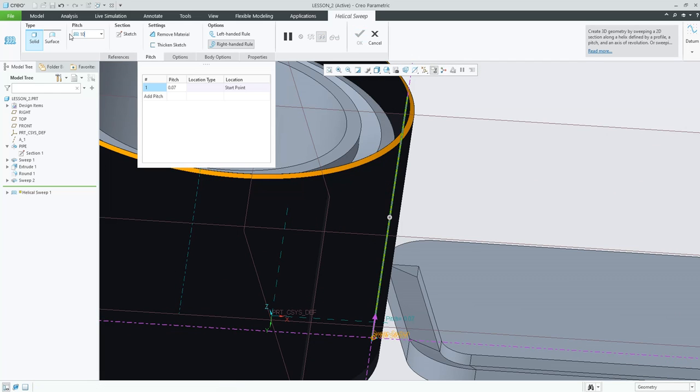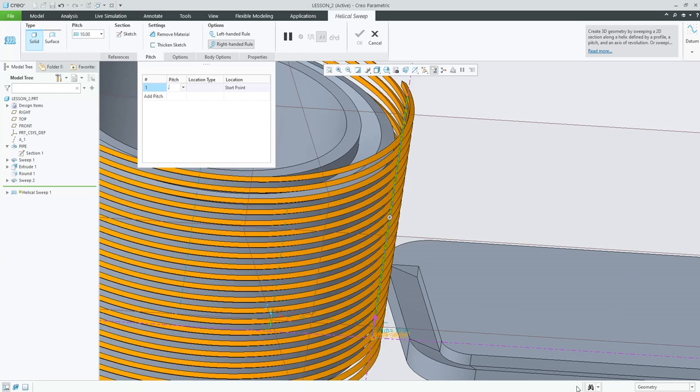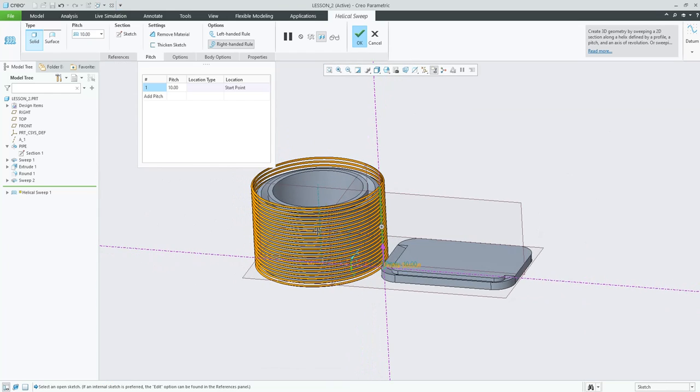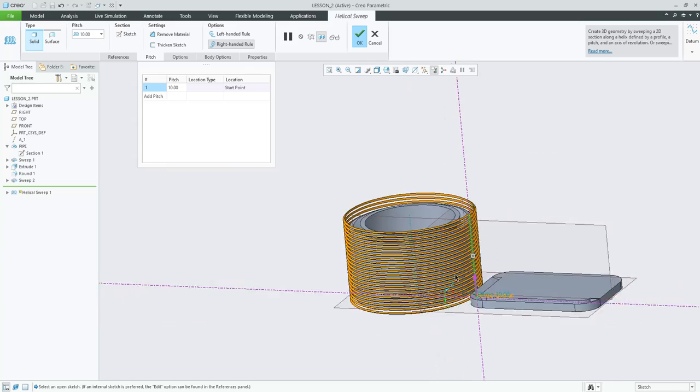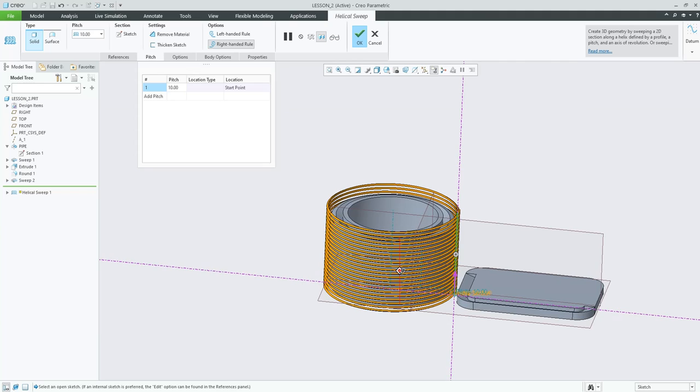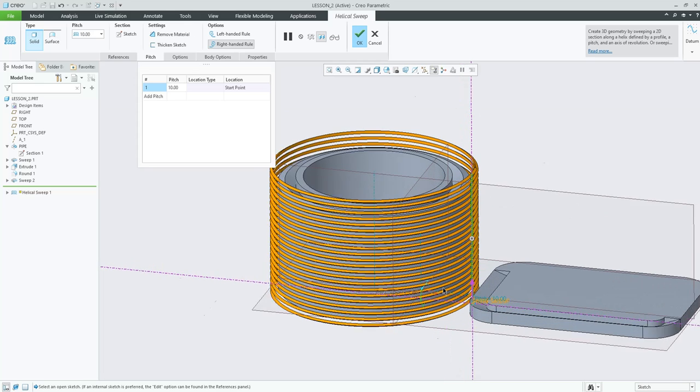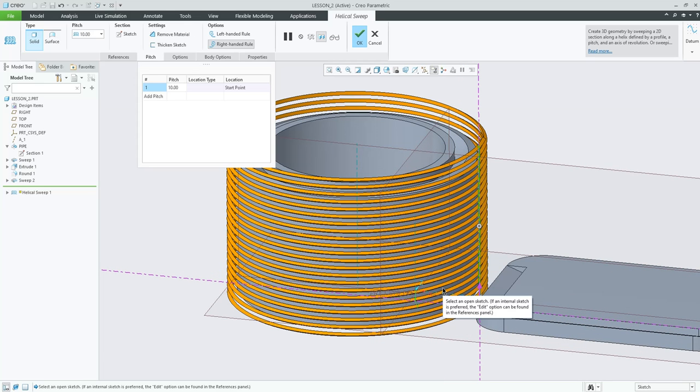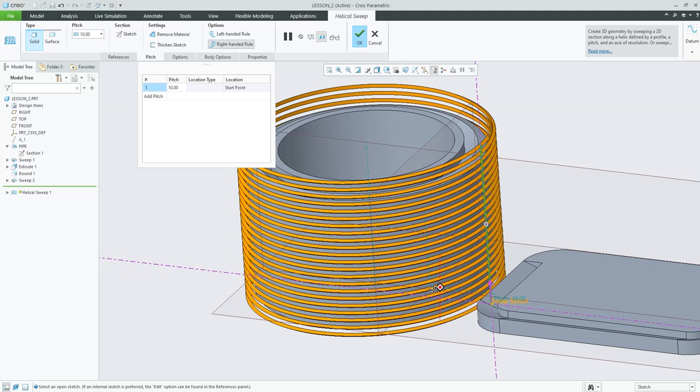In my experience, this little red X that shows up down here only works in certain features. Maybe that's been addressed in 8.0, but in the past, if you're stuck on a feature, it's best to just wait it out, because pushing that red X can fail the software and put it into non-responsive mode. So it's best to wait it out if you can. If it hasn't responded in like an hour, you're probably done. That's why I always recommend saving often whenever you have a large assembly you're working on.